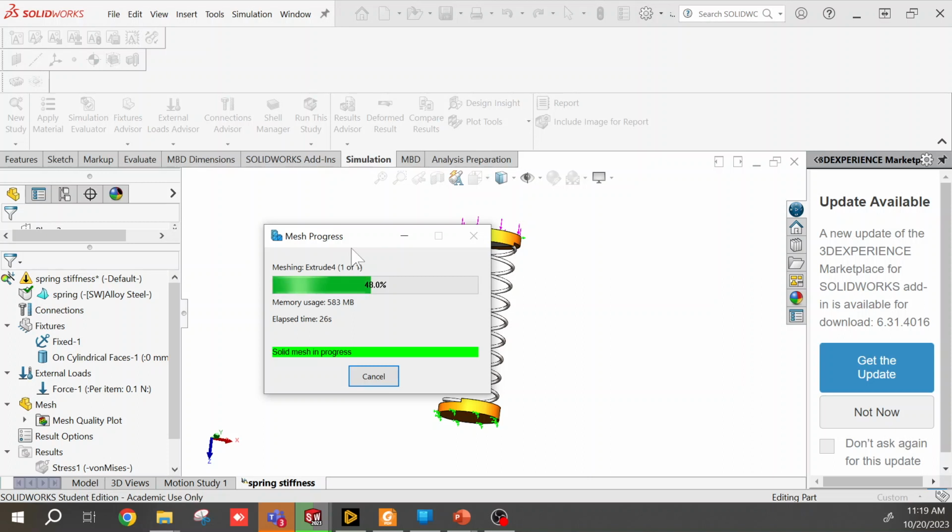Using this type of approach, like just an auto method, you kind of get what you pay for. Sometimes if it's simple geometry, it looks really good. We'll see an example of that. Sometimes it's terrible in the results. You have to go and touch it up a lot. And I'll show you ways of influencing the mesh to do what you want and capture the geometry perfectly, or as perfect as possible.